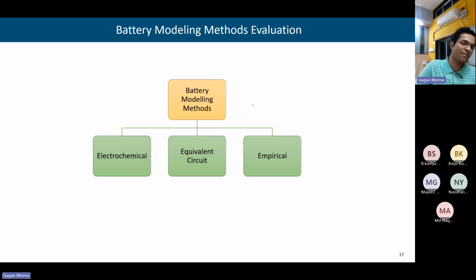The most commonly used model for optimization is that the discharging power will be within 0 to its maximum limit. Similarly, charging power is also between 0 and its maximum limit. And then charging and discharging cannot happen simultaneously. Their product has to be 0.